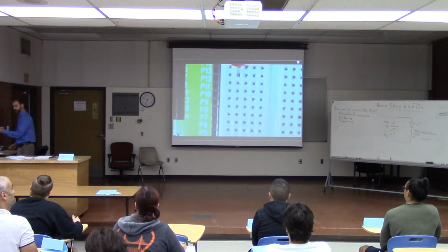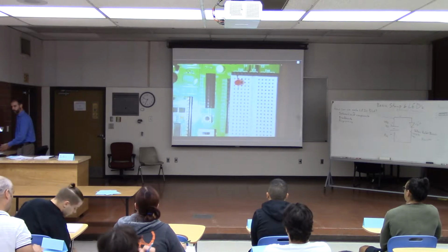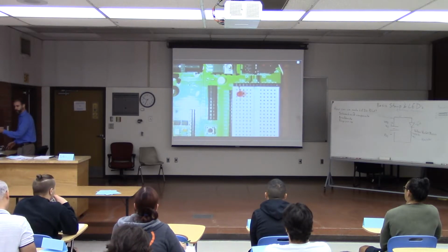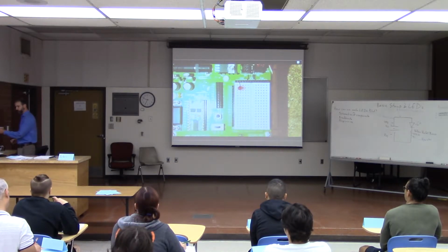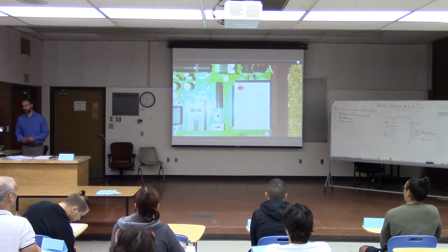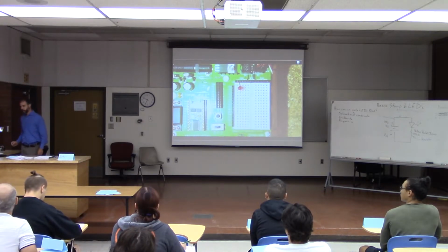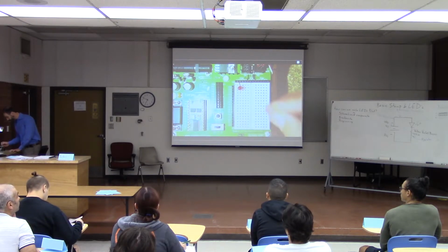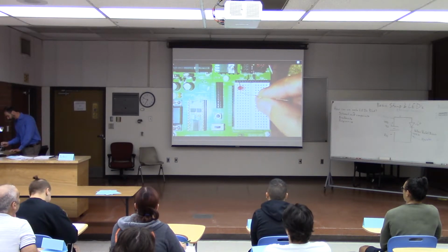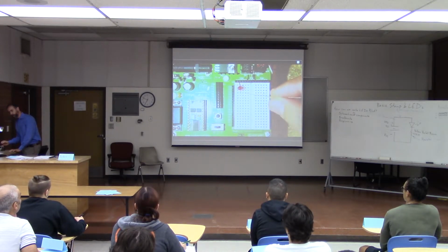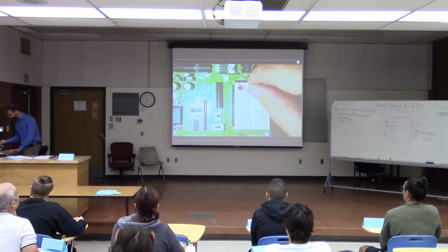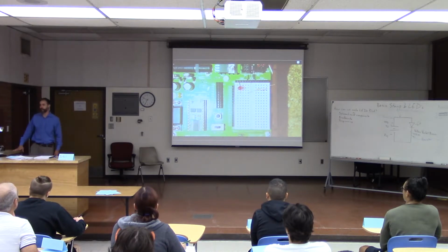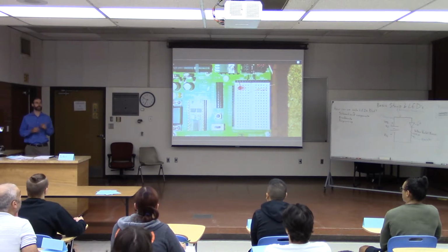All right, so we've got this resistor. And we're going to make a connection to the cathode of the LED, right? So remember, the cathode is this end, and we plug it into this hole in the breadboard, and that hole is connected to every other hole in this row. So if we plug this resistor into another hole in that row, now the resistor is connected to the cathode of the LED. You with me? Questions about that?